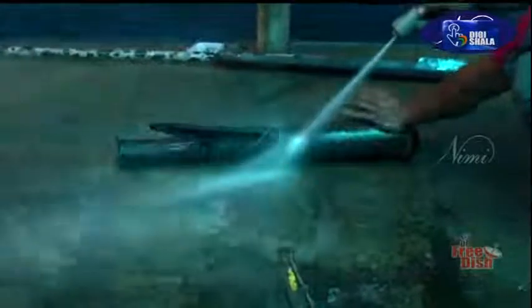Once again, scrape the carbon buildup in the exhaust thoroughly. Now, it will be easy to remove the carbon layer due to heating. Gently tap the muffler assembly to the floor to remove any carbon particles inside. Also blow compressed air over the muffler and exhaust pipe.